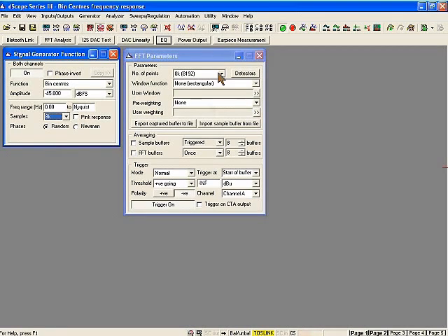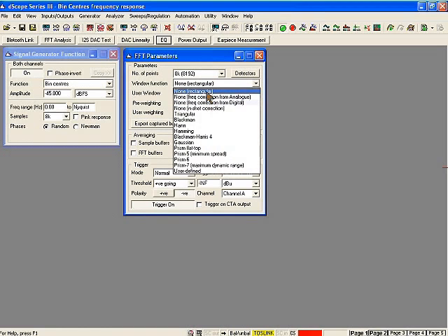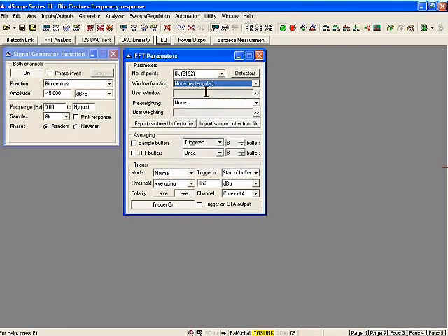What I have done is I have configured an FFT here in my FFT parameters with exactly the same size, exactly the same number of points, 8,192. And what this allows me to do is to use a rectangular window function, which will impart no spectral smearing on the signal, provided we can ensure a synchronous analysis condition. And having done this, I can then use my FFT measurement, which is a relatively fast measurement compared to, for example, averaged noise measurements or a sinusoidal sweep.